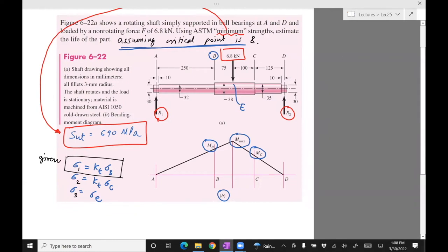Yeah, there will be. So in this case, you will be able to do this with finite element. The only issue is that whenever there is a stress concentration, finite element has problems because the stresses grow very quickly, and then the question is how small a finite element you need in order to capture that stress. So there are problems there, but nevertheless, yeah, you will do it.